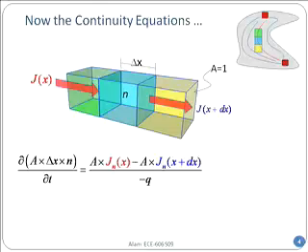Now, how does it relate to the current? Well, that depends on whether the number is growing or coming down, depends on how many are coming in and how many are getting out. Just like in this room, let's say students are constantly flowing in and some of them are leaving. So the number growth within the room will depend on the flux of electrons coming in and the flux of electrons getting out. Now I have divided it with minus q in the denominator because these are electrons and I want the number. And so in the J sub n, there is already a minus q. Remember that this is because it's the electron current density.